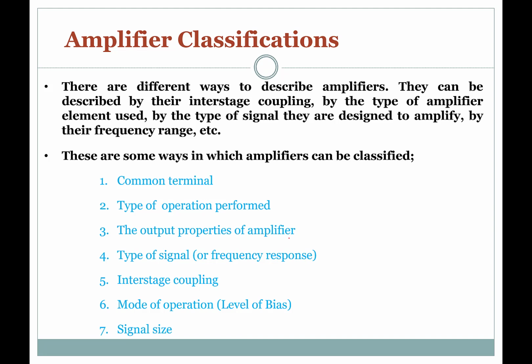Basically, an amplifier is an electronic device that accepts some form of input signal and then gives us a bigger version of that input signal. So for instance, if this block here is set to be an amplifier, and we have an input and we have an output here, assuming the input here is A, if it goes through this amplifier, this amplifier would have something we call the amplification factor or gain.